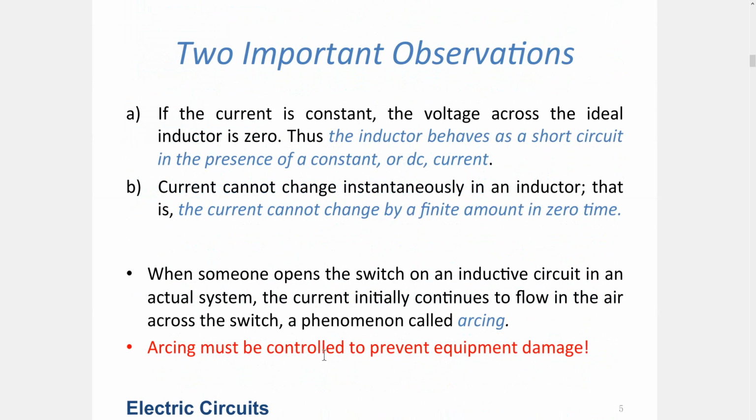When this on and off event occurs, it can be represented mathematically by a step function or a delta Dirac function, which occupies a very short amount of time. So a very high voltage can be generated across the connected inductor, which will cause arcing. Basically, you create a little lightning, which also creates some sound.